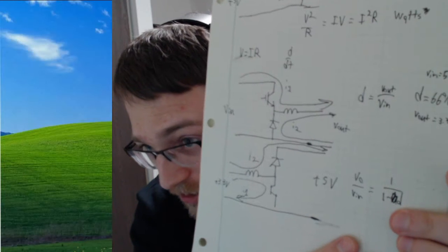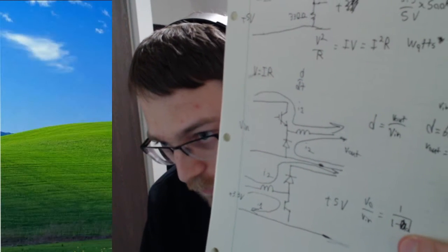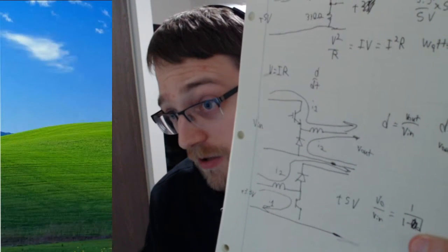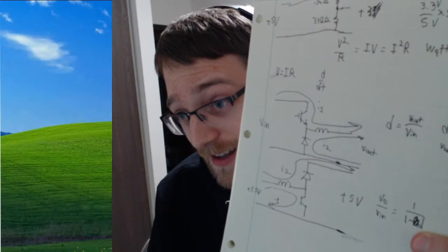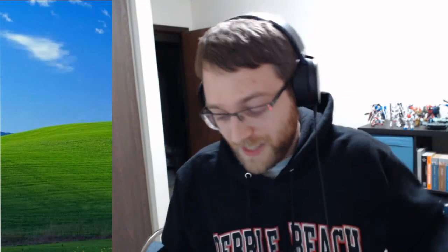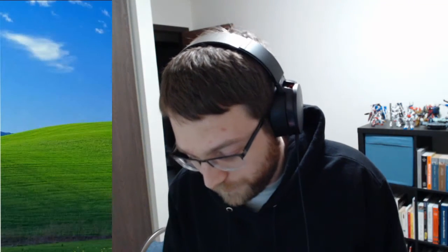Which is sort of correct here, because the ratio of output voltage to input voltage is 1 divided by 1 minus the duty cycle. That's why it's called D, because it's called the duty cycle. 1 minus D on the bottom side under there. So, that's how you can control what your output voltage is going to be compared to your input voltage. So that's a lot of fun.